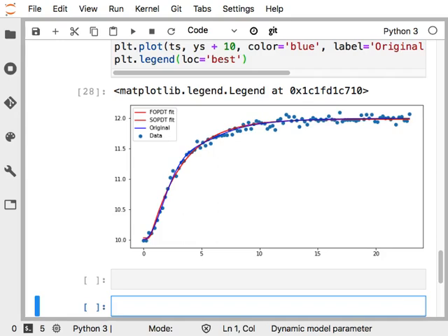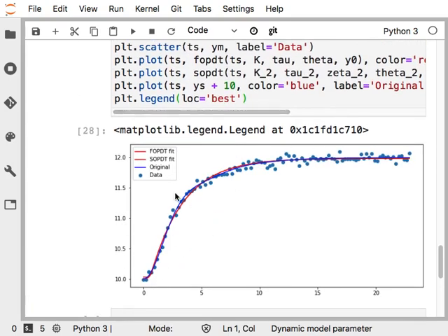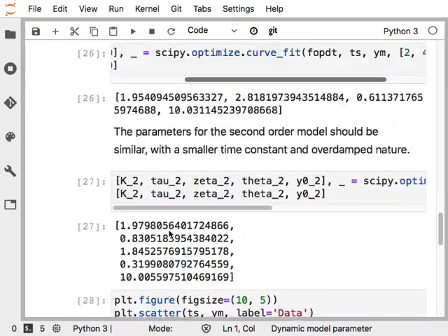So this strategy is basically the same kind of strategy that you can use there, and that would be necessarily nonlinear. An important thing to understand here is that in most cases when we have a generalized response function like this, the parameters are deep inside of that function in ways that are not easy to linearize. It is kind of possible for the first order response, there is a little bit of manipulation that you can do if the dead time is not very long. You can take logs and then get back to linear regression, but that's kind of an edge condition. It's not very reliable in my experience.